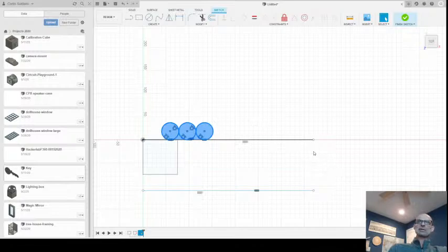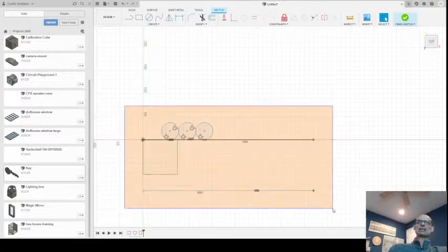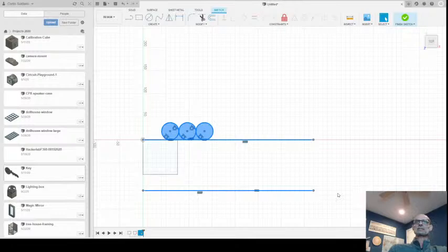If I right click and drag, oops, that's something I need to do. You're still left mouse clicking, by the way. You're just dragging to the right or left. In this case, we're going to drag to the left. And anything touching my bounding box will get selected. So you'll notice that that line is selected. If I do it this way, both those lines are selected. But if I'm going this way, neither of those lines are selected because you have to have everything that you want selected within the bounding box for that particular selection. So that's a little bit of a pro tip.